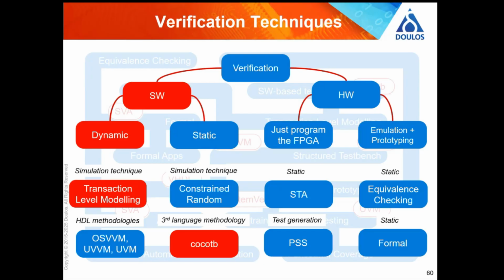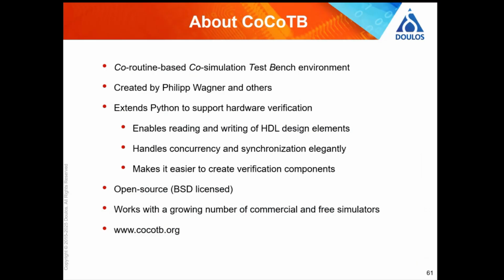Something else you could do is use a different language. Even if your DUT is in VHDL, perhaps you're doing an FPGA, it doesn't mean you can't use SystemVerilog to do your test benches, because SystemVerilog, especially in combination with UVM, is very, very powerful. But another thing you could do is use a completely different language. Why might you want to do that? Well, SystemVerilog takes you 5 days to learn, and UVM takes you another 4 days to learn. And we would be very, very happy to sell you a training course. Of course we would, because it's what puts food on my table, and you're very welcome. Our courses come highly recommended.